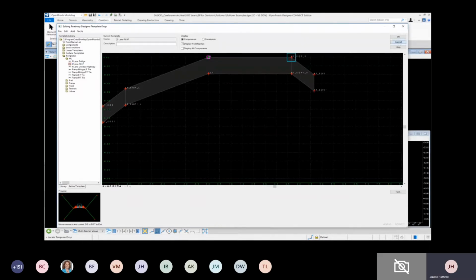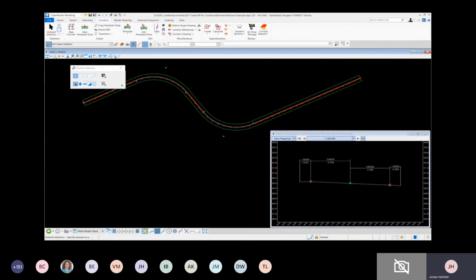So let's see this in action by simply going into the corridor itself. Right now, you can see within here, we have a dynamic section. And you can see that we have the 7% algebraic difference on the high side in this right-handed curve. And you can see the 2.2 difference, obviously making the 7. Low side, the planar lock. Now that's an easy example, and that's what we always had. So there's not much new there. So let's go to the second example.